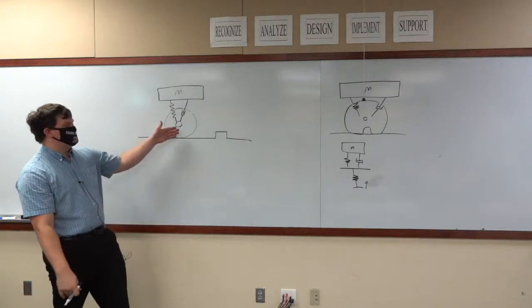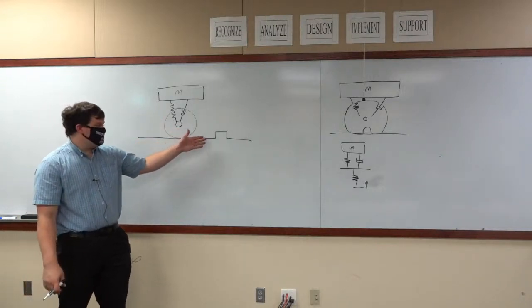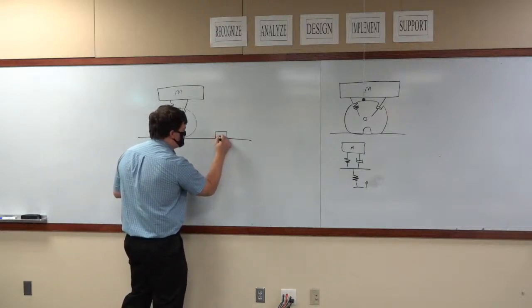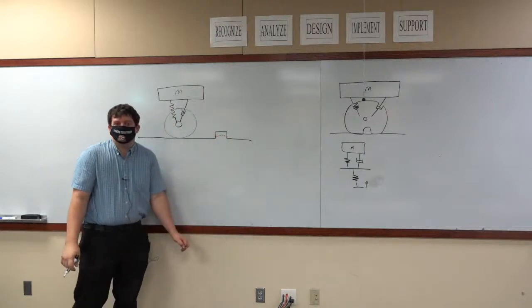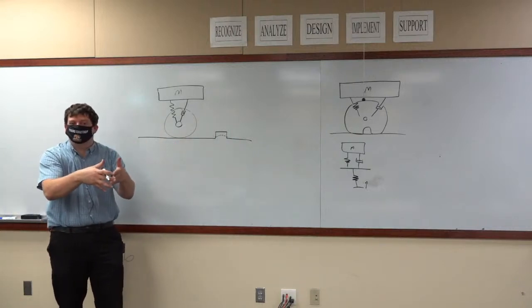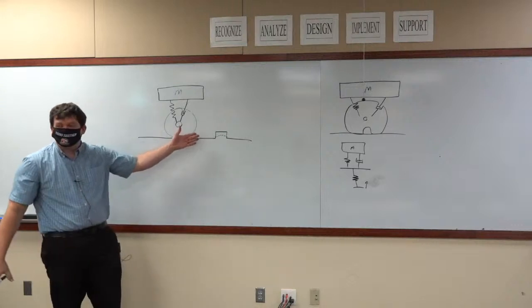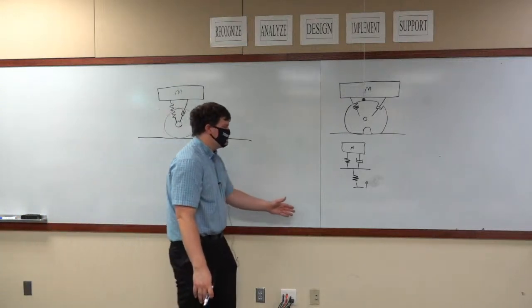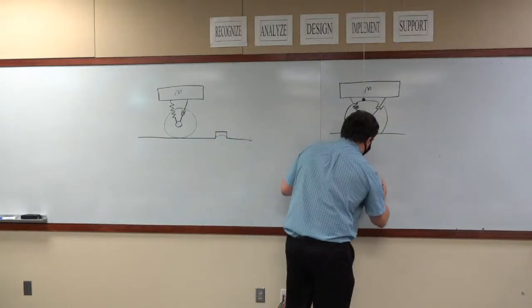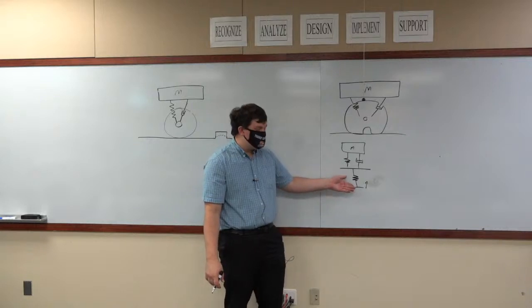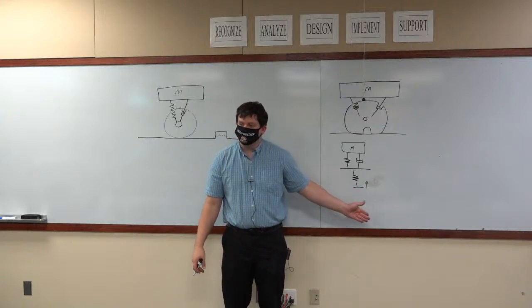You can't run over this bump and say, well, I have a force limitation, so I'm only going to run over part of this bump. The bump's got to look like this. No, it's not going to do that. A tire is not going to suddenly go into the road. It has to go over the road. That's the displacement relationship. So you are going to have a forcing function that is based on the compression of this spring.